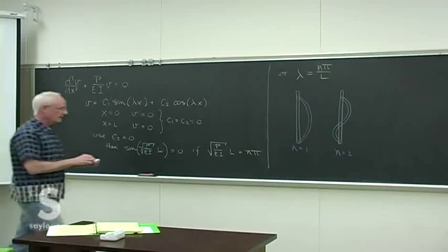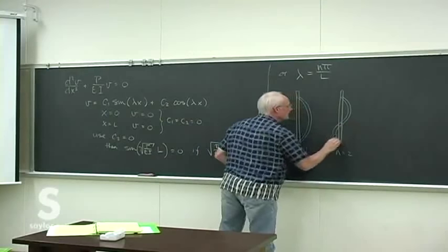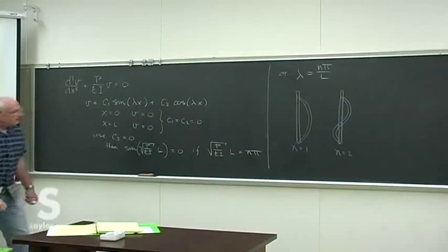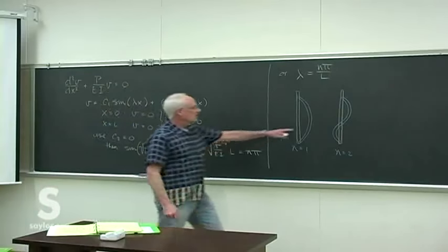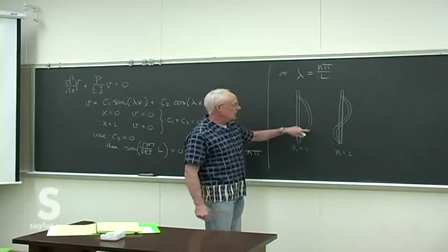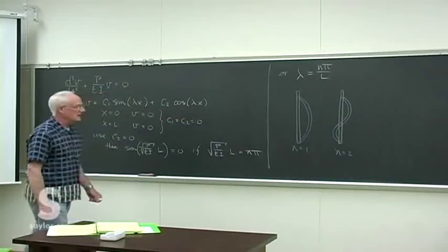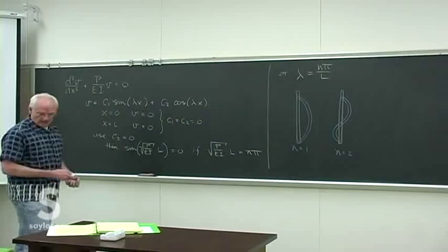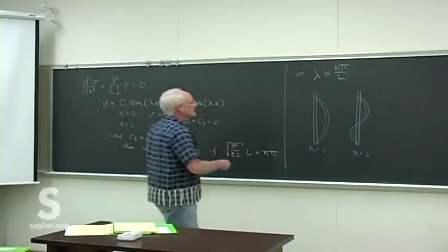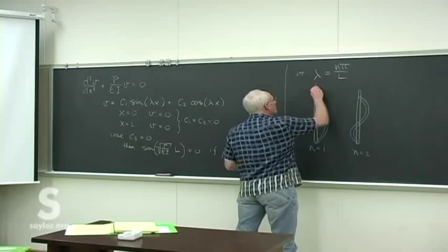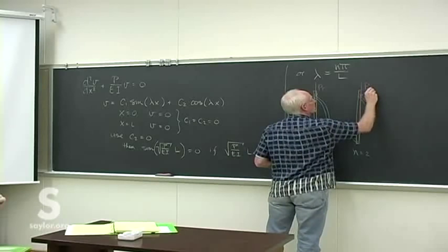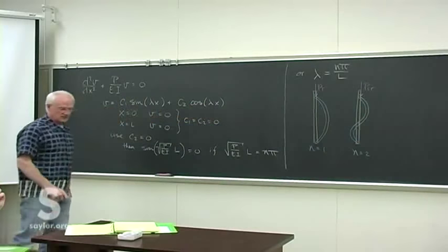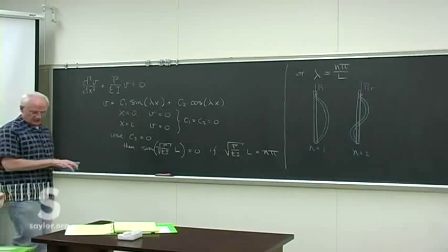This second mode of failure we could guarantee if we fix the beam at a midpoint so that it can't deflect side to side, then this is the more likely. In fact, the first mode of failure isn't even possible if we fix it at the end. What also happens, though, because of that, is that the critical load for that failure is much greater in the second case, in fact 4 times greater than in the first.